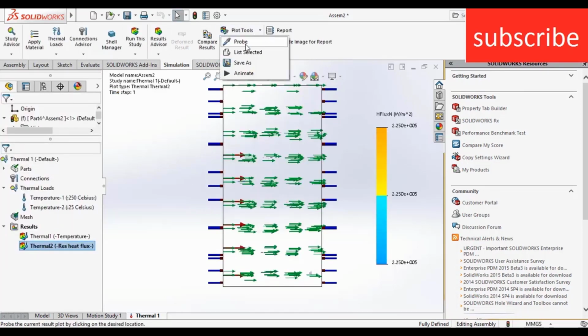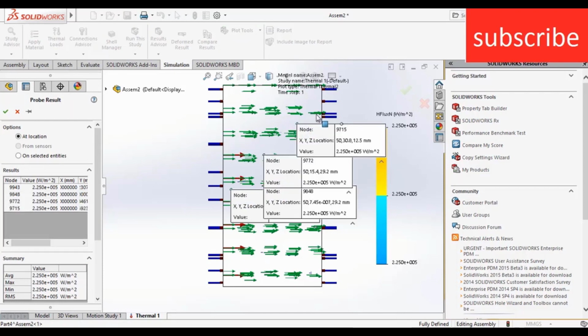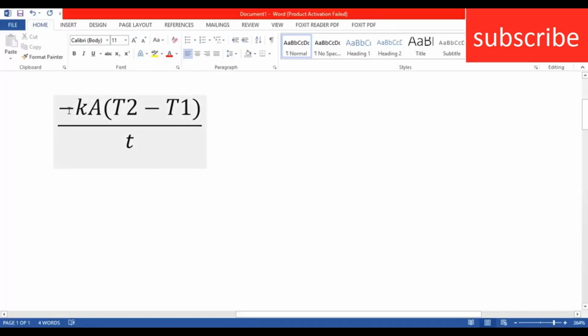Now click on plot. Here you see when I click anywhere, the value remains the same, 2.25 watt per meter square times 10⁵. Even if I plot a graph, you can see it is a straight line, because we know that Q is just Q equal to minus K A (T2 minus T1) upon T.